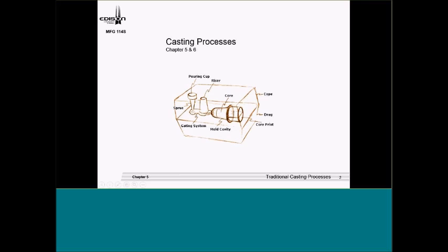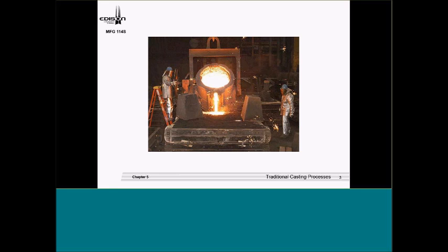And then we look at the gating system. I talk about the pouring basin, and the sprue where the metal goes in and goes through the gating system, if you have a gate or a runner. And then we have the riser, and I talk about the purpose of the riser, which is to escape gases, but we also use it so that when we pour and we see metal coming out of the riser, we believe we have a complete fill.